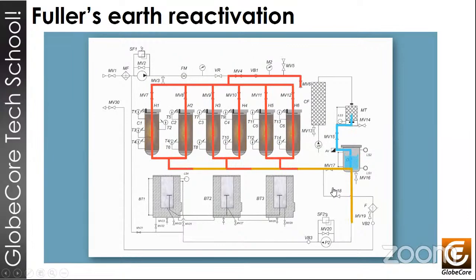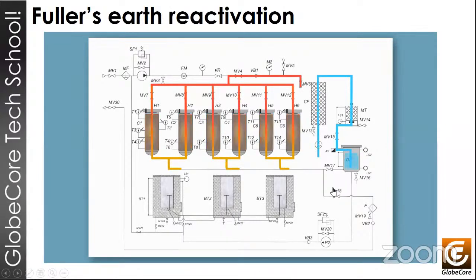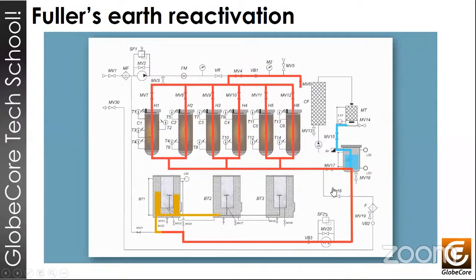So when the temperature in the columns rises, the remaining oil is transferred to the contaminated oil container. And the absorbent is blown through with a strong stream of air. And when the temperature drops again, then the plant is ready to continue the dielectrical regeneration process. And this is a cycle that can be repeated 200 to 300 times. And as we've calculated before, this translates into significant amounts of regenerated oil on a limited load of sorbent.